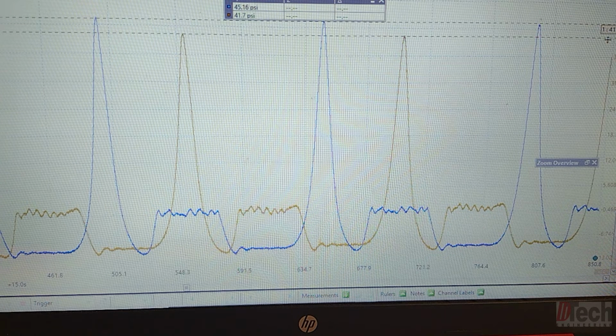The key factor for finding differences between the 3 tests I just showed you, relative compression, cranking in-cylinder, and running in-cylinder, the dead giveaway, the easiest one, was relative compression, which on all misfire cars is the test that I always do. Even on cars that don't misfire, if I suspect some sort of issue or anything, I always do relative compression. Again, this car was diagnosed in the first 5 minutes. The rest was just for detailed information and my own curiosity and trying to learn more as I go.